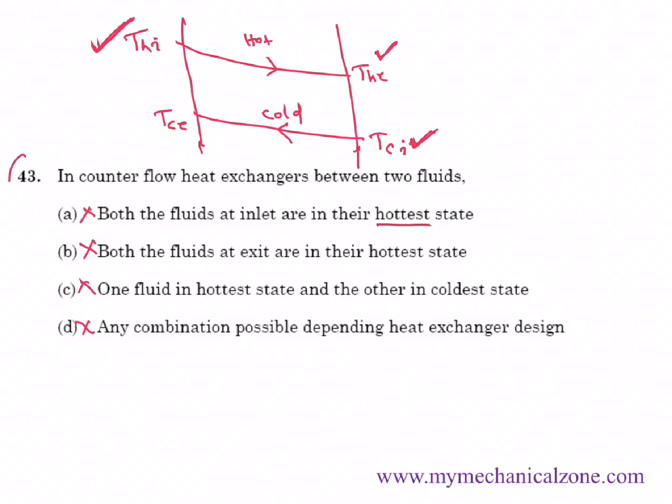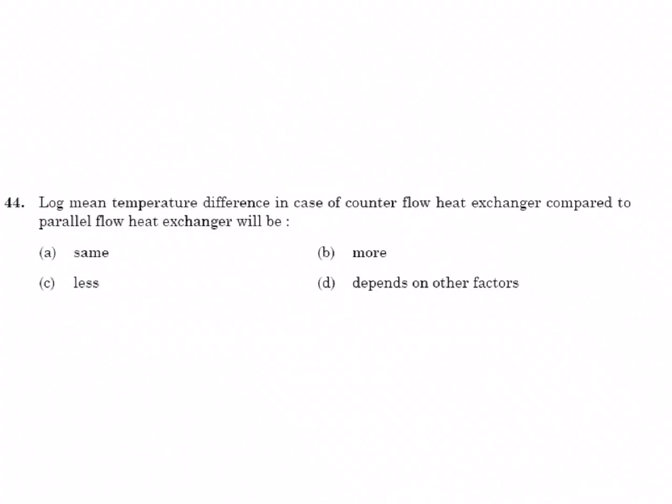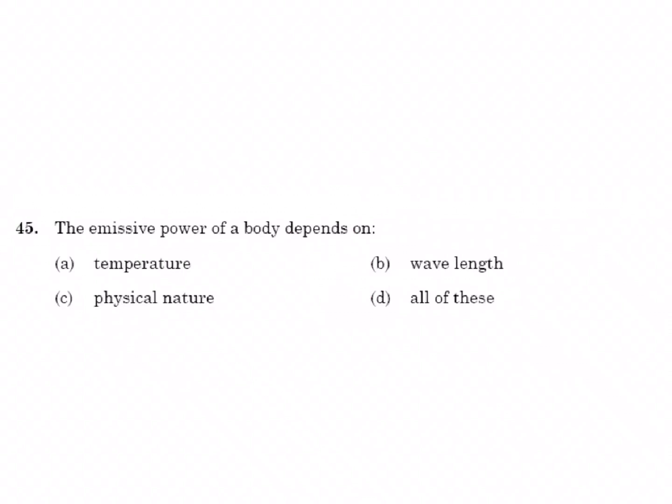So no option. They omitted this question also. Log mean temperature difference in case of counterflow heat exchanger compared to parallel flow heat exchanger will be... counterflow heat exchanger is more than parallel flow heat exchanger. So B is your correct answer.